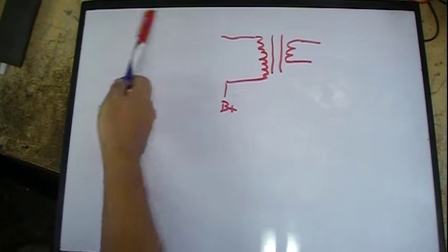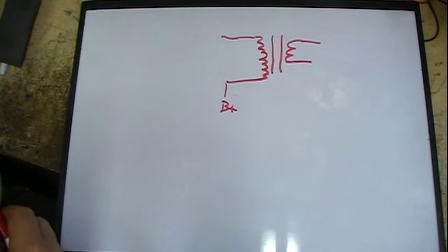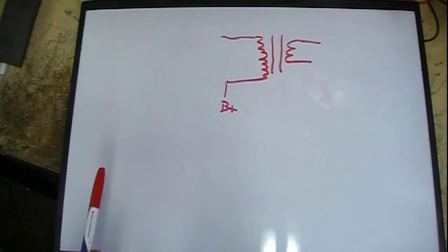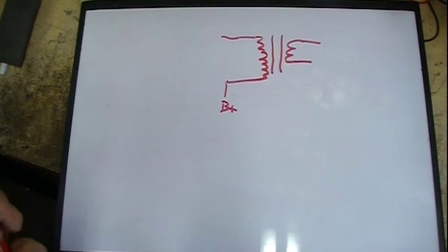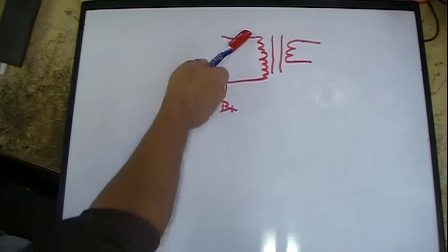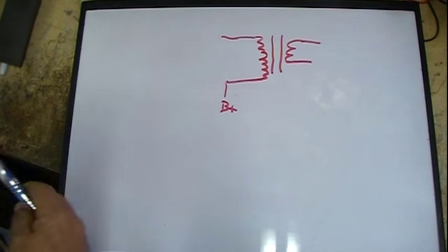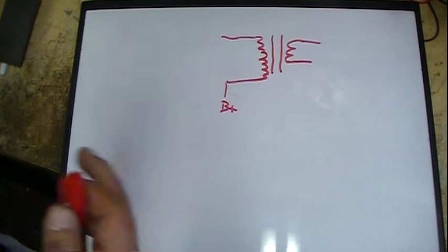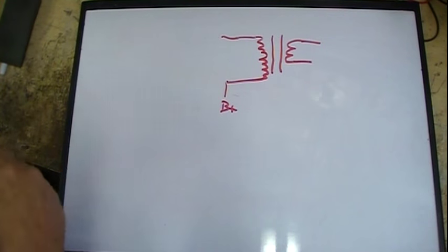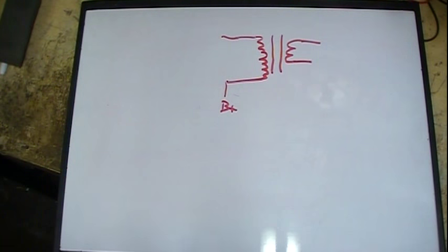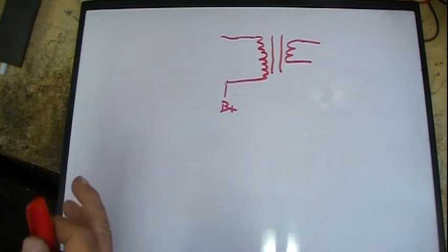When you look up an audio tube in a tube manual, it's going to tell you what kind of impedance load that tube looks for. It could be 6,000 ohms, 8,000 ohms, 10,000 ohms, something like that. But if you measure the average audio transformer you find in a radio, it's going to be a DC resistance of around 400 ohms or 450 or somewhere in there. There may be some as high as 600, some a little bit less than 400, but it's going to be somewhere in that area. A far cry from a few thousand ohms.